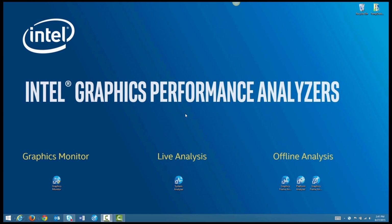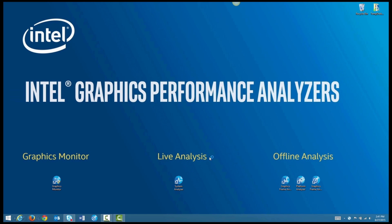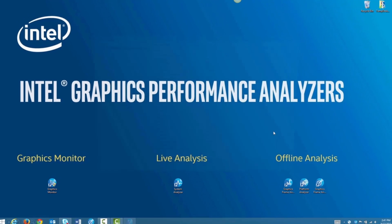In the workflow videos, we briefly went over live analysis. Today, I would like to look at Graphics Monitor and System Analyzer in more detail. So first, let's start with Graphics Monitor. First, we click on the program, Run as Administrator. You'll see Graphics Monitor is in our tray in the bottom right-hand corner. If we right-click on Graphics Monitor, we will see a couple different things. Let's first look at the profiles.